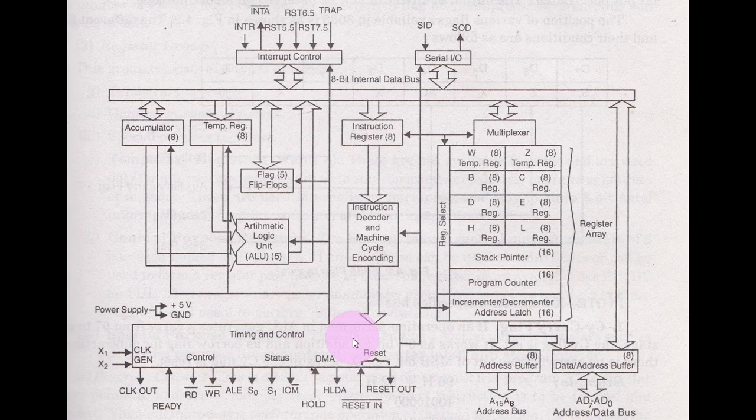That is, they are able to make permutations and combinations of already stored instructions in this instruction decoder and achieve a certain task. So that's what we meant by programming. A user will make permutations and combinations of all the 246 patterns that were available to him as a programmer, and those patterns in a particular sequence which achieves some task is called a program. That program is read byte by byte into this instruction register, because this is of 8 bits, and that's how this complete digital circuit became multifunctional. So that's what we have seen about this architecture.